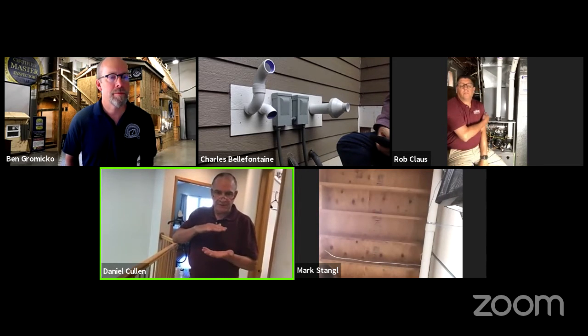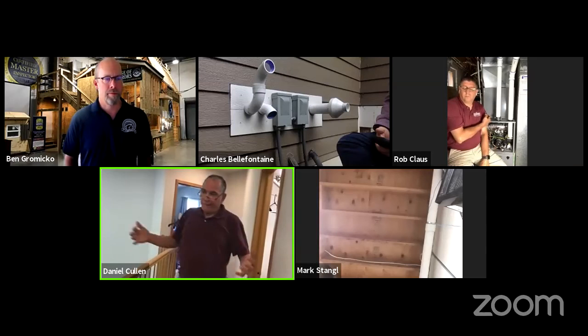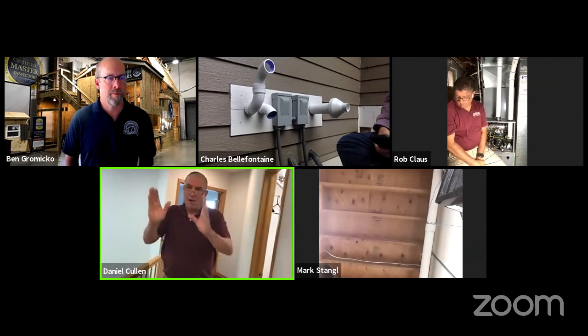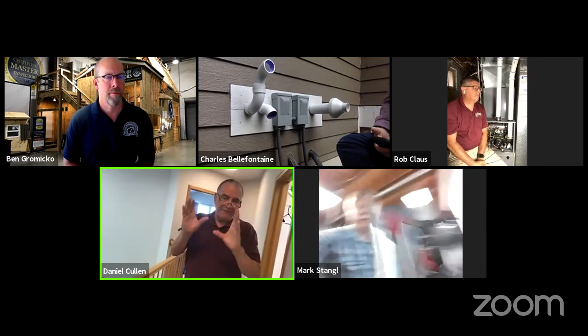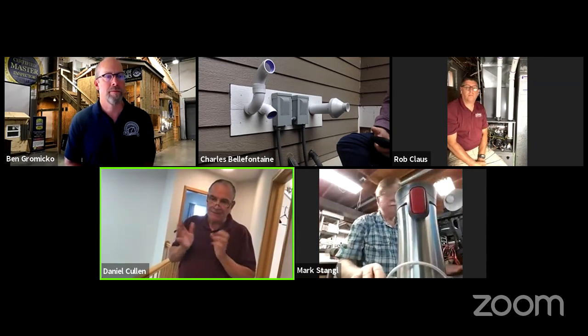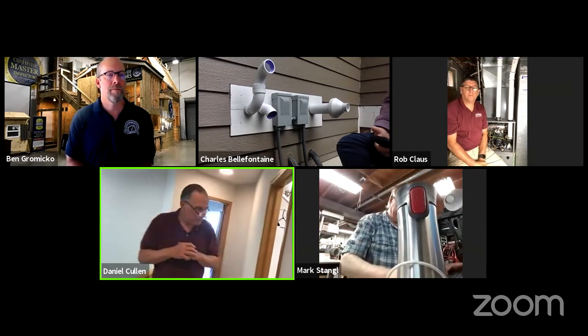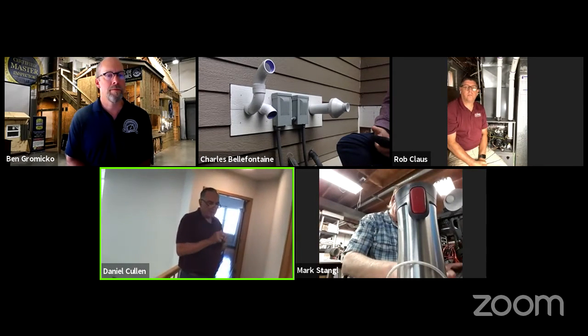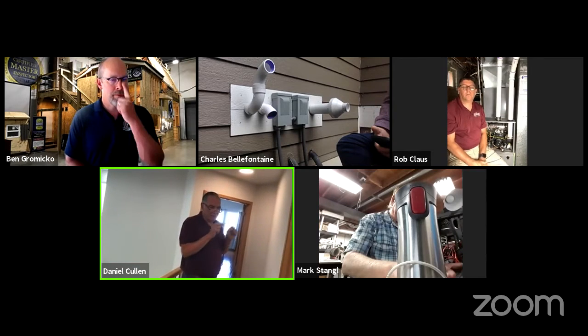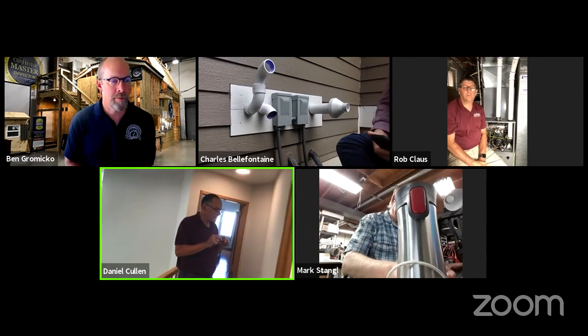We have a lot of different framing joints there. And the typical approach, which is still code compliant, believe it or not, just a rectangle of fiberglass shoved in there, doesn't work very well. So it's nice to foam those or to cut in blocks of rigid board insulation and caulk those into place.